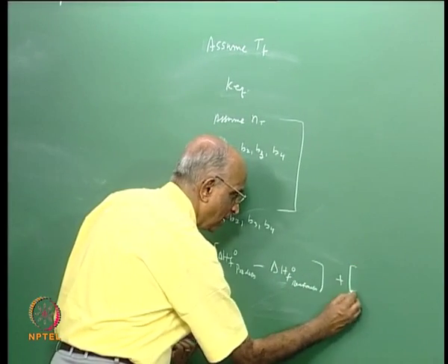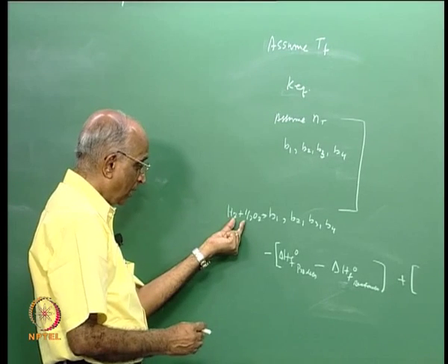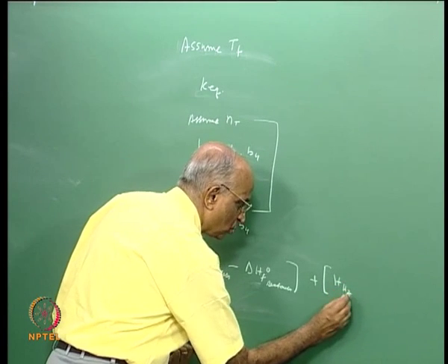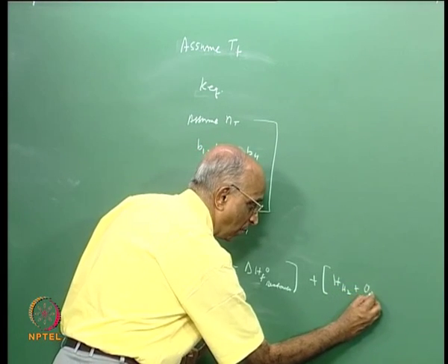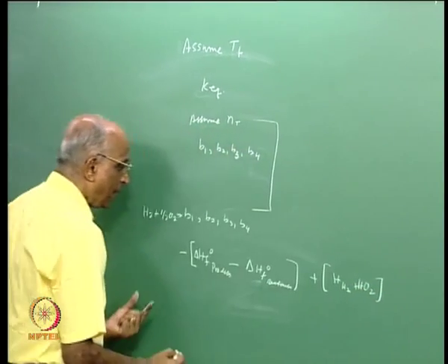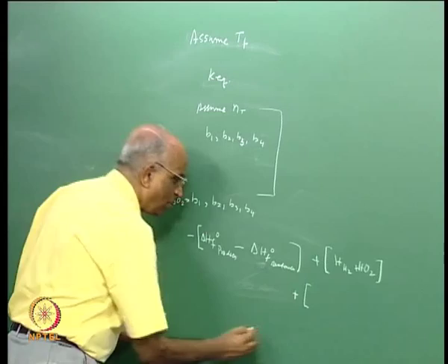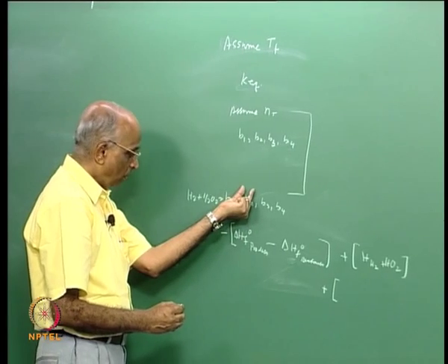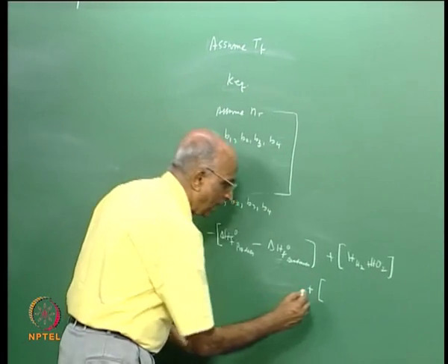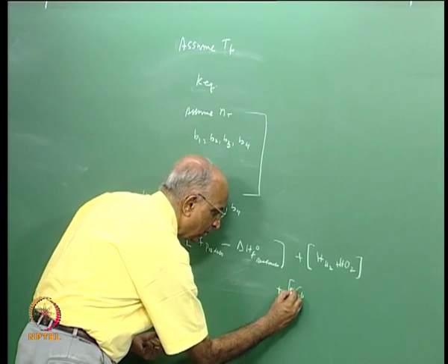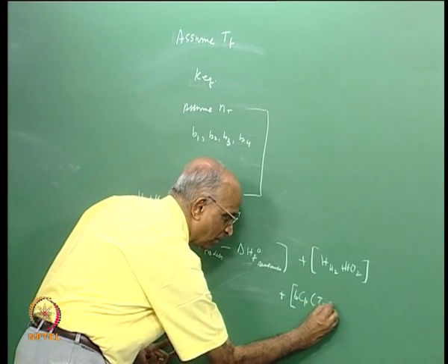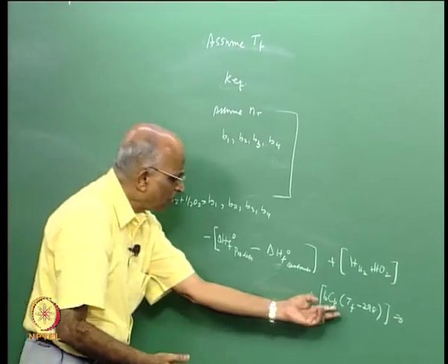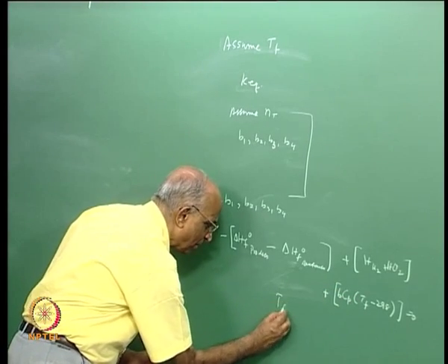That means I say I have the liquid phase, I have the latent heat phase, I have the vapor phase, therefore I have the heat required for H2, that is one of the fuels. Similarly, I have for the oxygen what enthalpy is required, and again the balance of heat goes into sensible heat for the products and also latent heat as applicable for H2O, which I do not explicitly write. And this must be 0, right? This goes into this and to raise the temperature. Therefore, I get the new value of temperature.